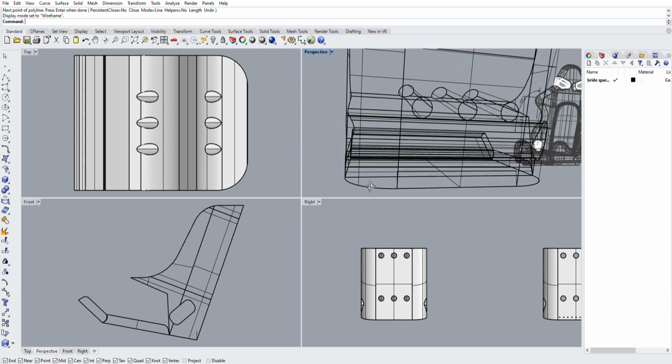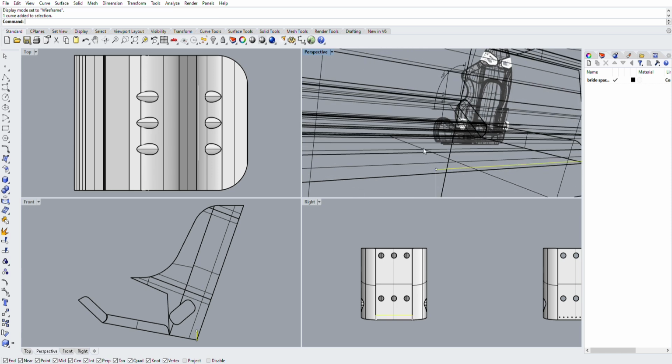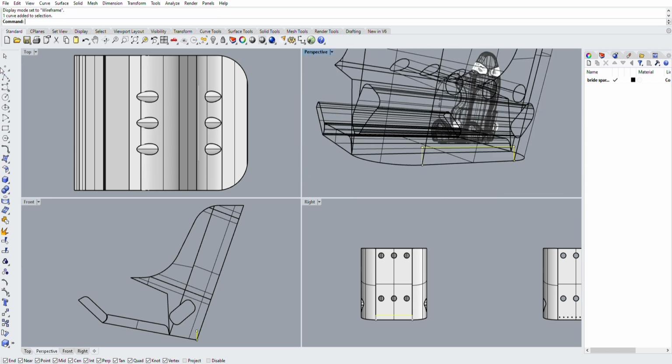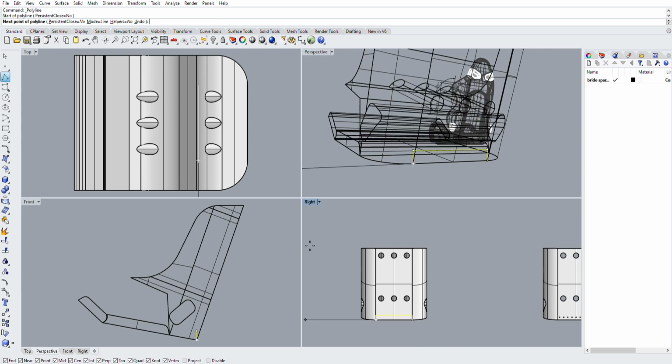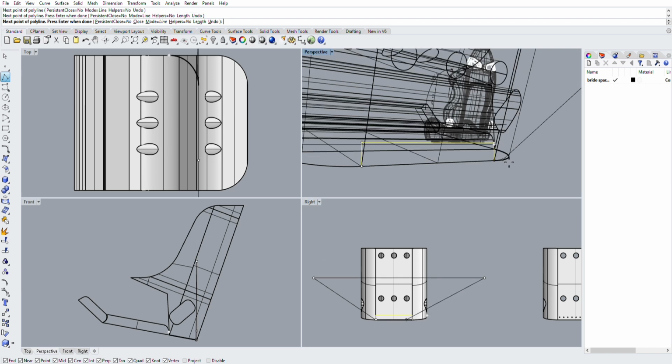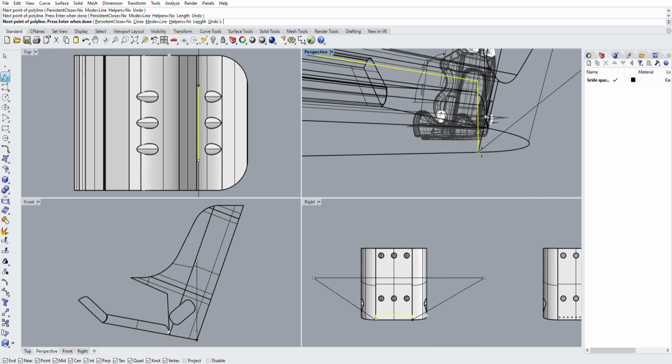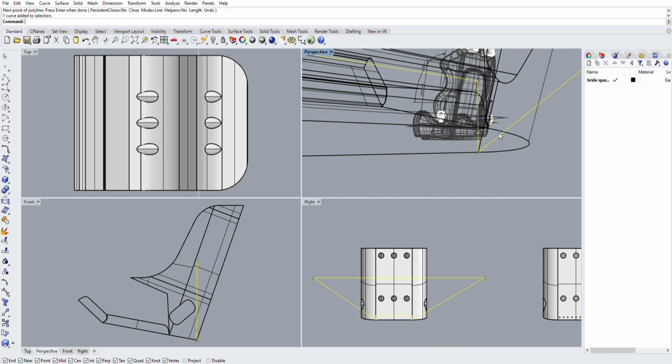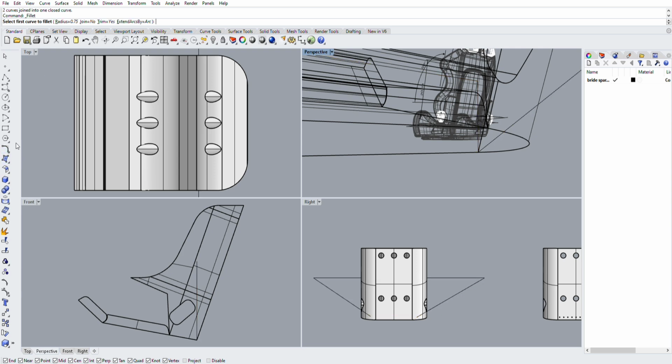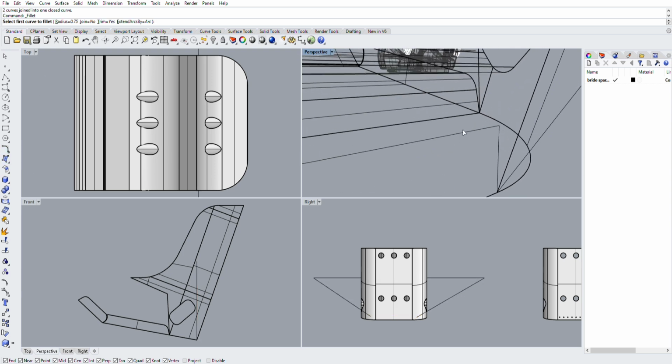I'm converting this back to a polyline view because then I can see it, because the line was hidden within the solid. And there is no logic to this line I am drawing. I'm just drawing it outside so that it removes material. The beauty of having multiple views is I can zoom in on different views and get the points, and I know in the 3-dimensional view that I'm actually attached to the point I need to be at.